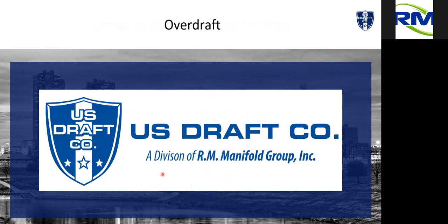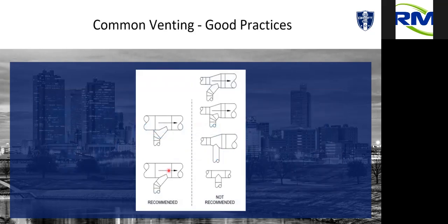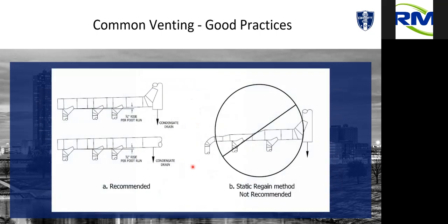Real quick, we had a question come in about common headers. Does it have to be the same? Does it have to be straight? Absolutely not. So we've had many systems where we'll pick up two boilers, we'll 90 degree and grab two more boilers. It does take a little bit more to balance, and we can talk about that actually here in a second, the best way to balance those, but absolutely not. We've had several where we'll have multiple fittings in that common header.